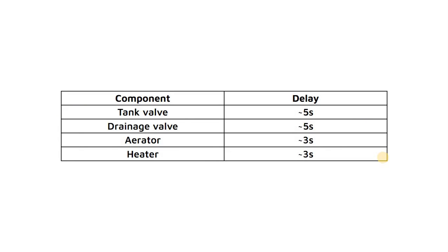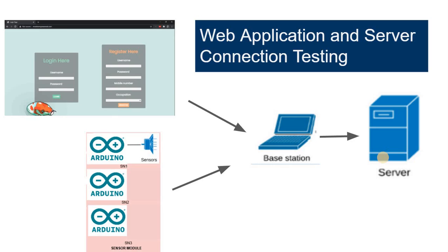The switch would take approximately 2 seconds to switch. The tank and drain valves had the longest delay due to the solenoid valve used taking approximately 3 seconds to fully open or close. Next is the web application and server connection testing.